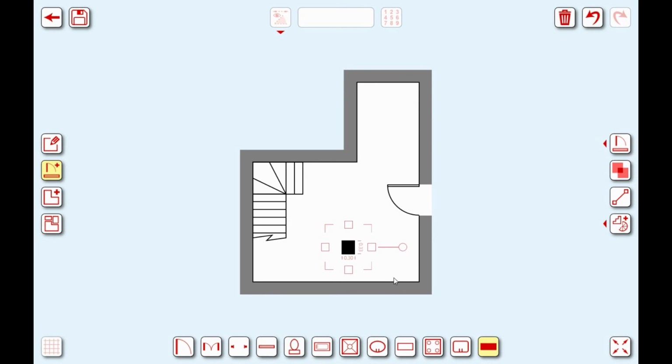So let's drag into this corner here. If we pull the block in, we'll see it snapping with the green corners. What we can then do is resize this block again using the drag handles, and then we can move it along that wall. So in this case, for example, maybe a chimney breast, and we can pull it off and snap it to the wall at will. And we can also increase the size out, so the width as well as the actual length.